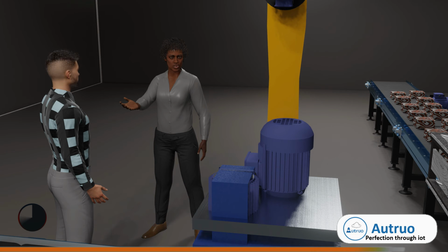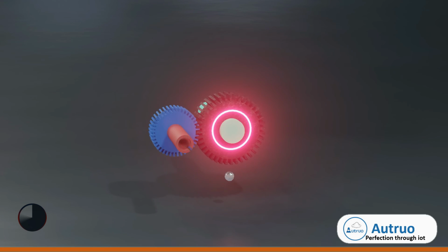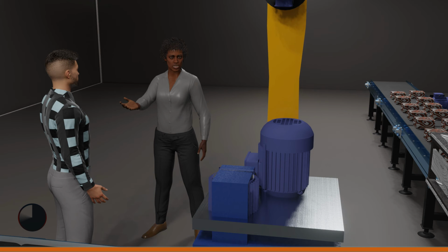However, the reverse is the case with the gear of larger size and more speed at the driven. It can be seen that the force acting on the teeth is further away, and with this, lesser force is applied to the driven. Although the speed is on the increase in this configuration, the generated torque will be less.